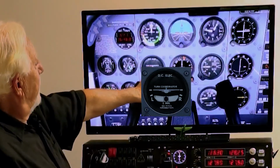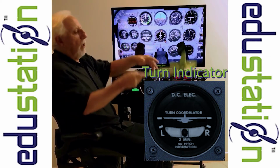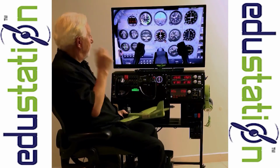The last instrument here is called a turn indicator. And if you match the wingtip to the first mark, your plane will turn a 360-degree circle in 2 minutes. And we use that for training.